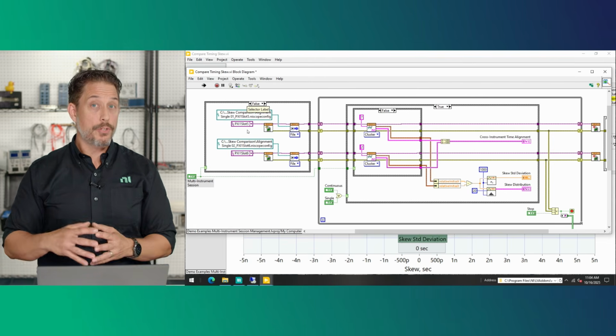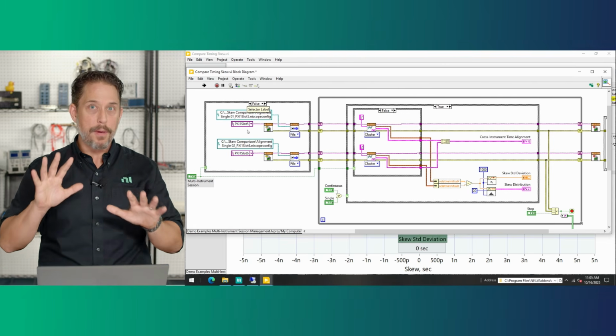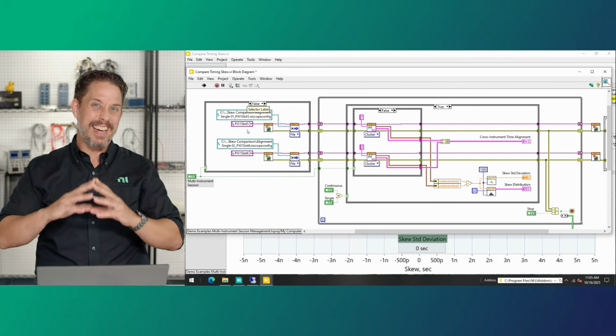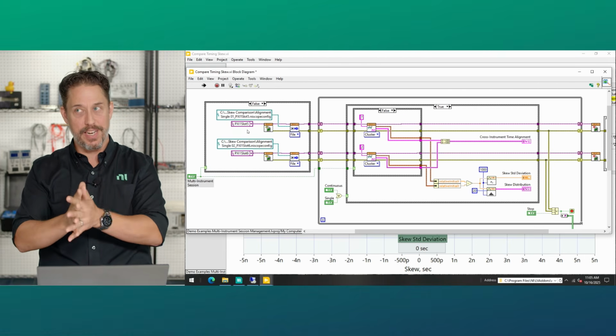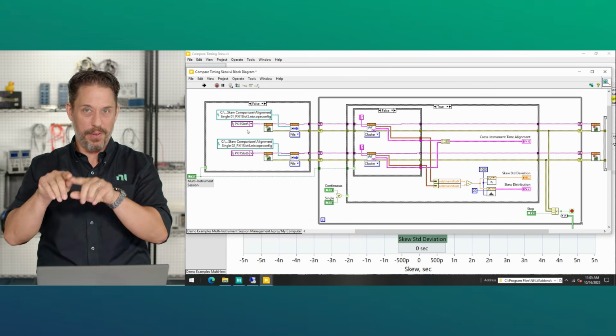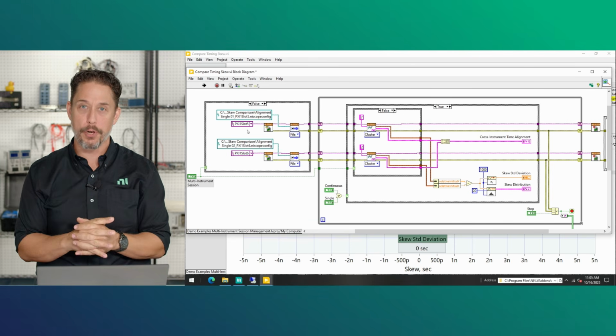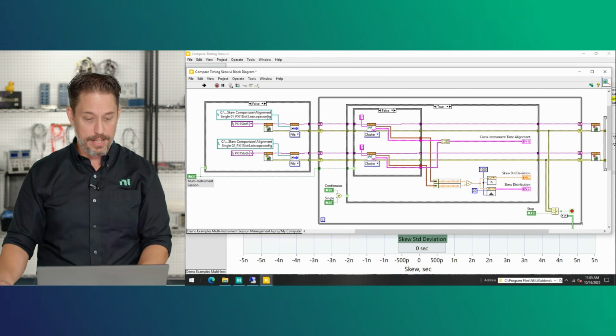Now, what we're going to do here is look at this actually running live and see what this looks like for not the 4 instruments that we have in these slides, but rather just the 2 separate oscilloscope cards, once again, looking at those 2 separate aligned channels. So we're going to start off by comparing what it looks like when you don't take any effort to get those 2 instruments aligned, except using the exact same incoming signal. We kind of branched out one signal to both scopes to trigger off of. And let's see what that looks like.